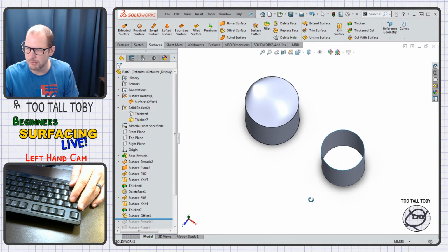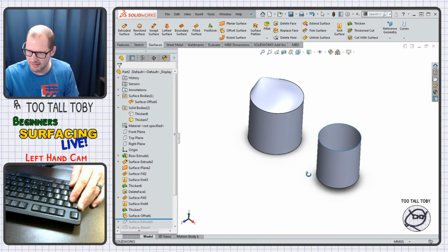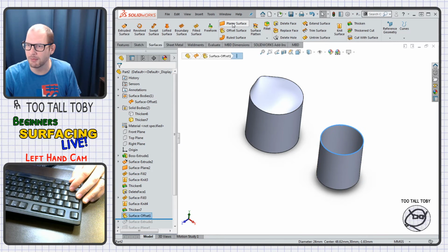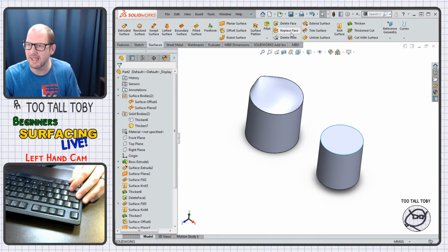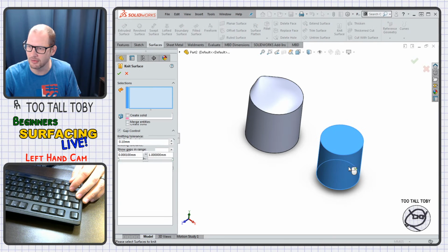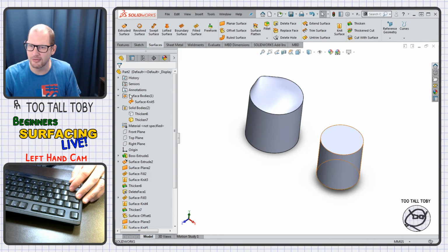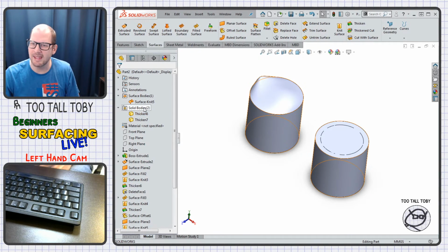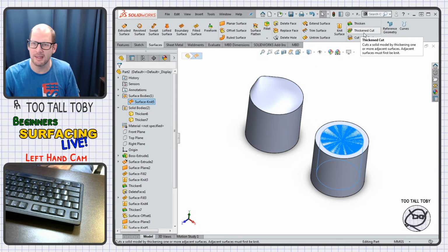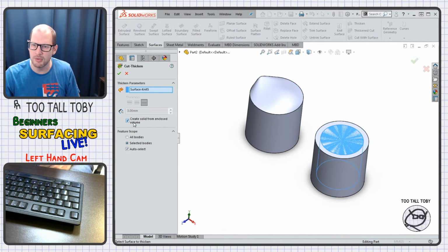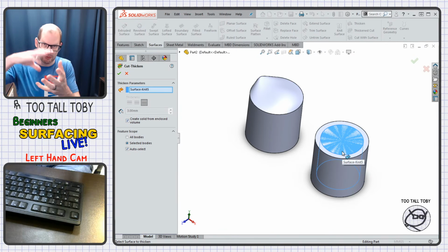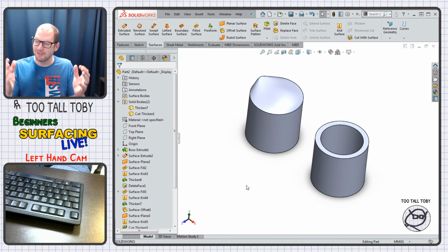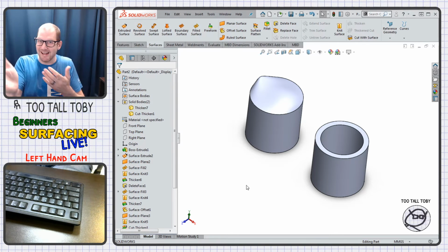We've got a surface body in here, which represents that offset region for the shell. It's capping that end. So we'll do a planar surface here. It's taking that geometry and making sure that it's one single surface body. So now you can see that we've got this surface body here, and we've got this solid body that it's sitting inside of, and then it's taking that surface body and performing a thicken cut command where it is removing the geometry from that surface region from your solid. And there's your shell.